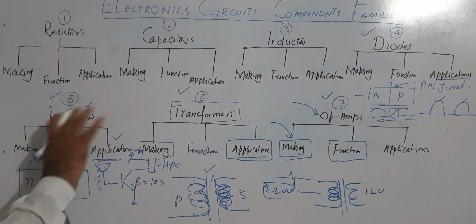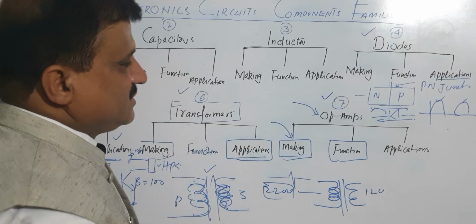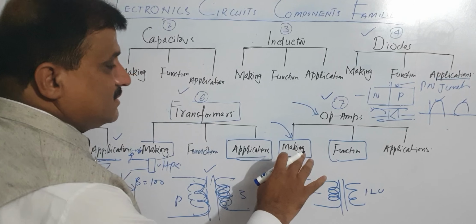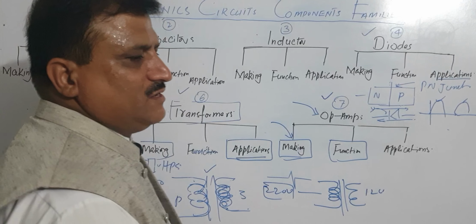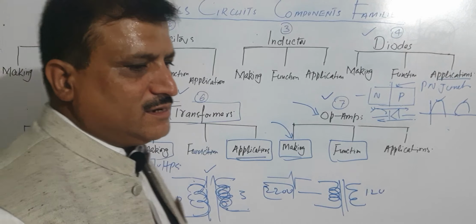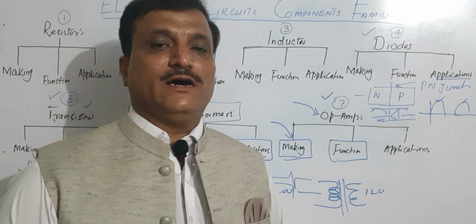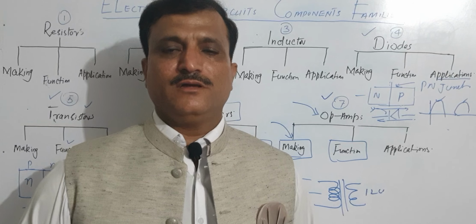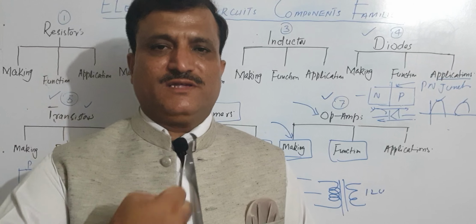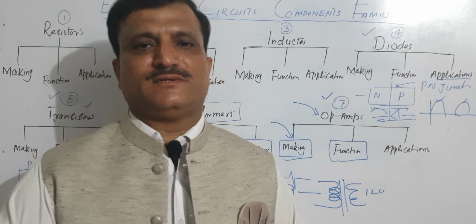The transistor is used to amplify the signal. This is also used to amplify the signal, because as is evident from its name, it is an amplifier. But an operational amplifier can lift or increase very weak signals, like signals in the nanovolt, microvolt, and millivolt range. It is required in practical circuits. Why? Because if we connect an ECG machine to different nodes of our body, those sensors pick up a very weak signal from the body, and we must amplify those signals in order to process them.